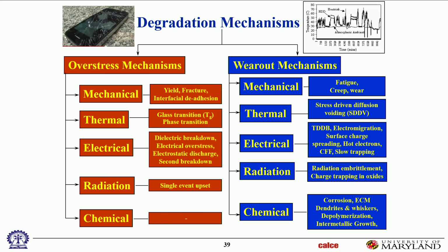And they're there for standard materials like steel and all. You just open a steel handbook, all the fatigue constants are there for different steels, aluminum alloys, copper alloys. They're all cataloged. We need to be able to do the same thing for metals, materials used in electronic systems. But the biggest challenge, like I said before, is the length scale. We're not dealing with steel bridges. We're not dealing with steel girders or aluminum beams. We're dealing with micron scale, nanoscale structures that are fatiguing, that are off the length scale of their individual microstructural